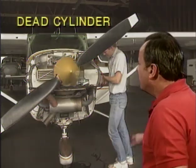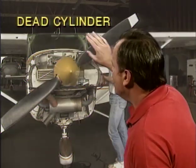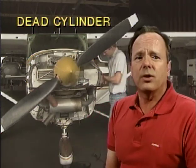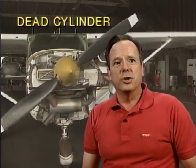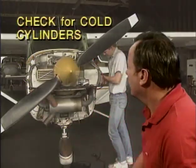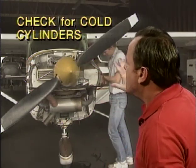Now, let's assume you're doing a ground check and the engine is running rough, and the magneto drop is normal and the manifold pressure is higher than normal for an engine RPM. What's likely the problem? Well, the problem is you have an entirely dead cylinder. The engine misses in both the left and right positions of the magneto switch. How do you find the dead cylinder? And the answer is go around and feel, very carefully feel, and check for cold cylinders, because that's going to be the dead cylinder.